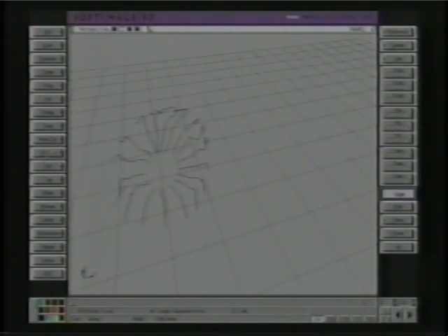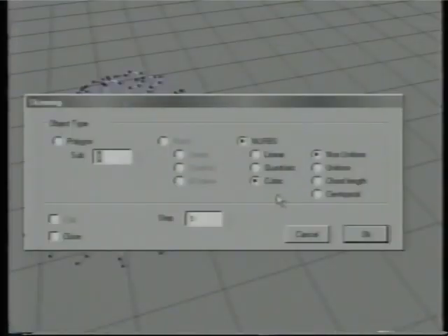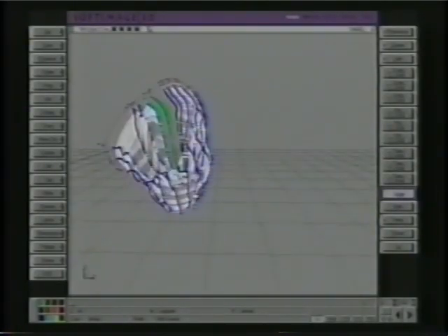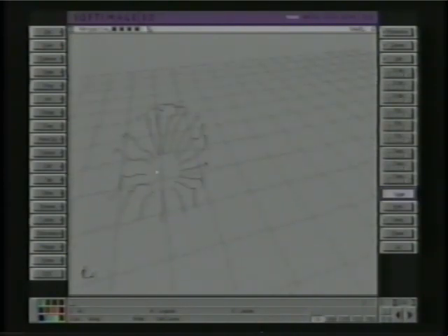So you do surface, skin, and when you're done, hit the right mouse button. You can choose between different formats, but most of the time you'd want cubic and non-uniform. This creates a big mass of points. The reason for this is that one of the curves has the wrong number of points. NURBS skinning will allow you to do odd numbers of points, but you get data that's really pretty unusable, so most of the time you want to make sure you have the same amount of points.